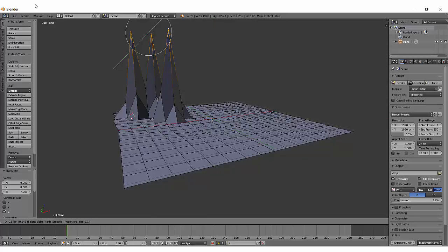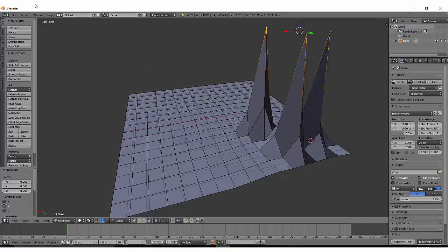Now press O on your keyboard so that it shows how much influence should be given to our mountain. If the circle is bigger, then the dimension of the mountain will be bigger. Basically go for a circle such that it covers all the points which you have selected. Selecting the circle size is nothing but deciding how much brush area you require. Now this is the figure after we have pulled up the vertices.